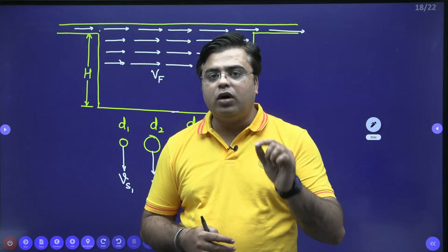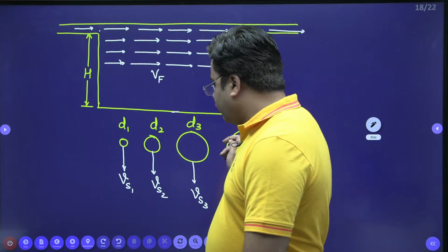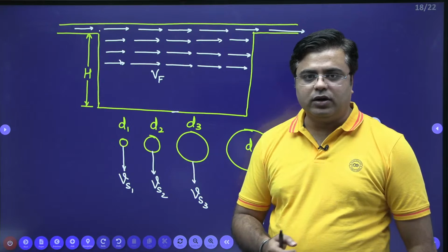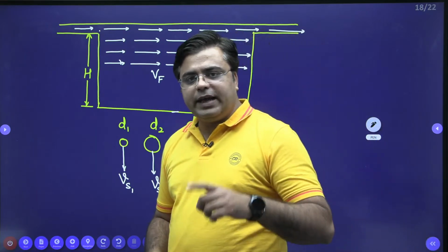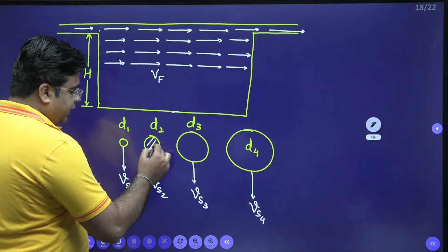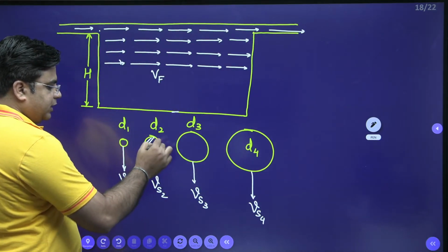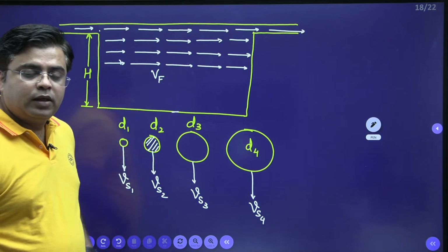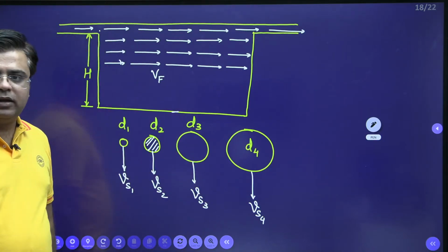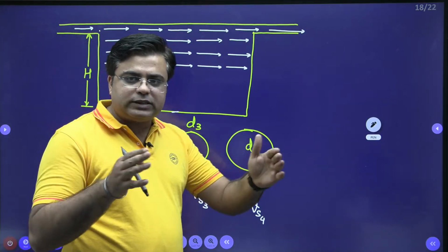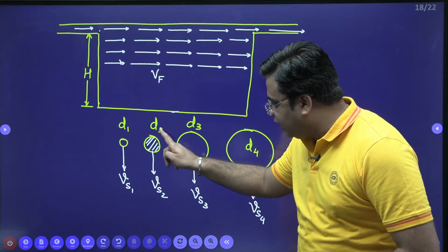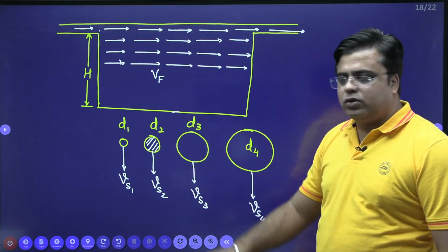That's why we do not design these tanks for the removal of all the suspended solids, especially the finer suspended solids. So we as engineers, based on our experience, take one size of the particle. Say I have chosen this size of the particle. Now I will design this tank for the removal of this size of particle. That is, I provide this much length to the tank so that sufficient time is available to this particle to reach the bottom of the settling zone.